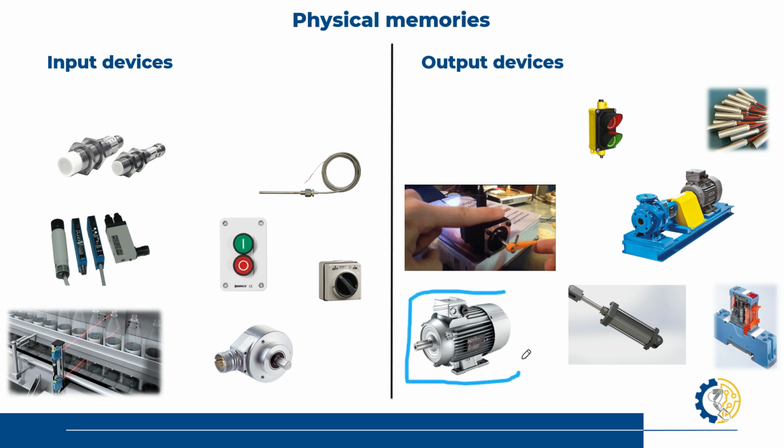For induction motors, start and stop, and for real data type. But if we assign a speed and we wish to gradually keep that velocity, in this case hertz, it could be RPMs, depending on the application, what data type would we need? If it's decimal, then these would be real because hertz we can send, for example, 15.4 hertz or 5.4 hertz as well. But the goal is going to be decimal. Okay? Now, pistons.